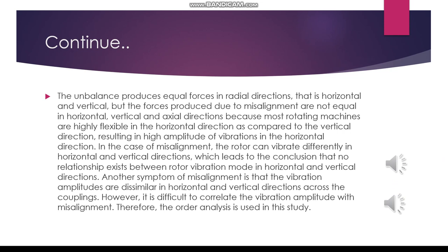In the case of misalignment, the rotor can vibrate differently in horizontal and vertical direction, which leads to the conclusion that no relationship exists between rotor vibration mode in horizontal and vertical direction. Another symptom of misalignment is that the vibration amplitudes are dissimilar in horizontal and vertical direction across the coupling. However, it is difficult to correlate the vibration amplitude with misalignment. Therefore, third order analysis is used in this study.